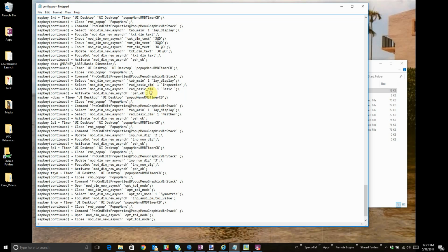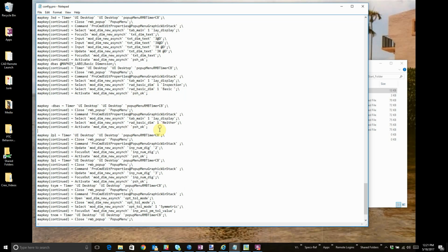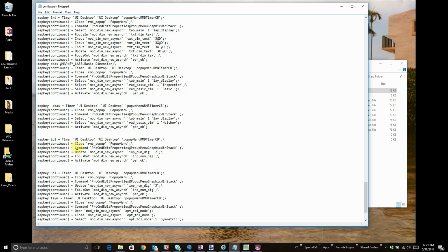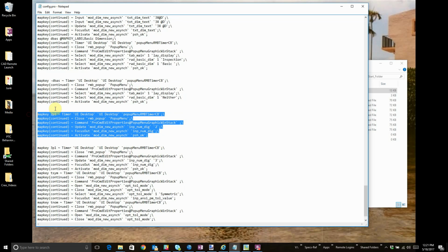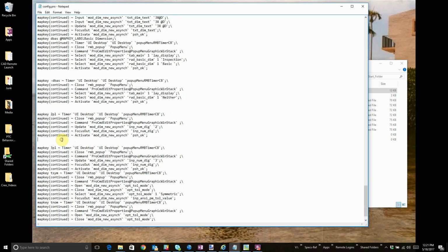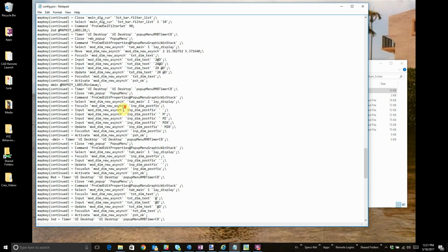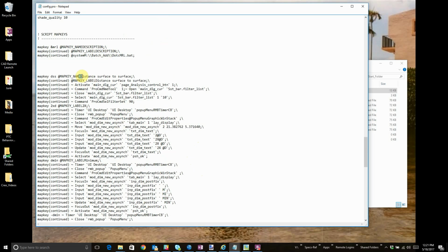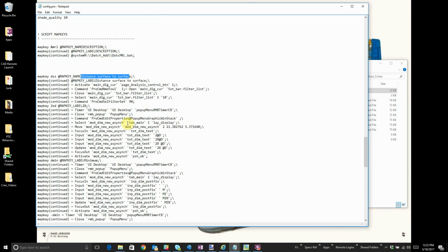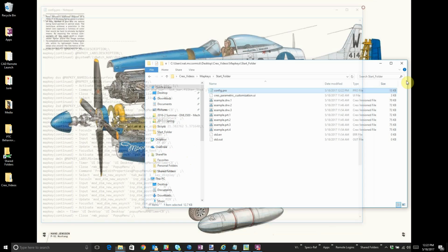So it is good once you save, especially a group of them, to come in and curate your config.pro. And you can see my original point, like the two places map key. I could come in here and just pop in a new one. This is your key sequence. So I could change it to 4 place. And right here where it changes the digits, I could change that to 4. And obviously if you have descriptions, like where's one with a description? Yeah, see, you could come in here and change the description also. So I think that's helpful. Don't forget to save when you leave your config.pro or you'll be sorry.